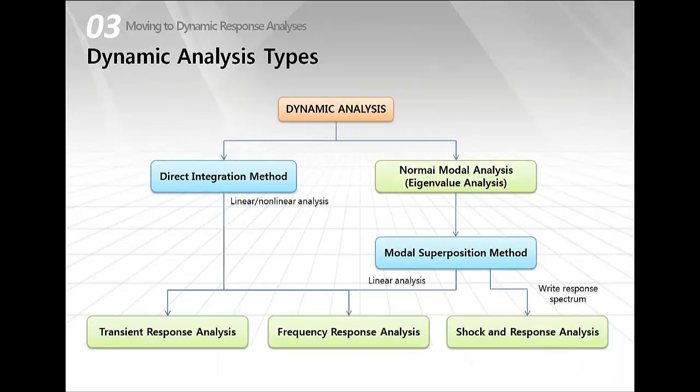So the next slide depicts dynamic analysis divided according to the solution algorithm used. We can consider an algorithm based on the direct integration method or the modal superposition method. As you see, both response analyses, I'm talking about the transient response and frequency response, can be analyzed using both methods.